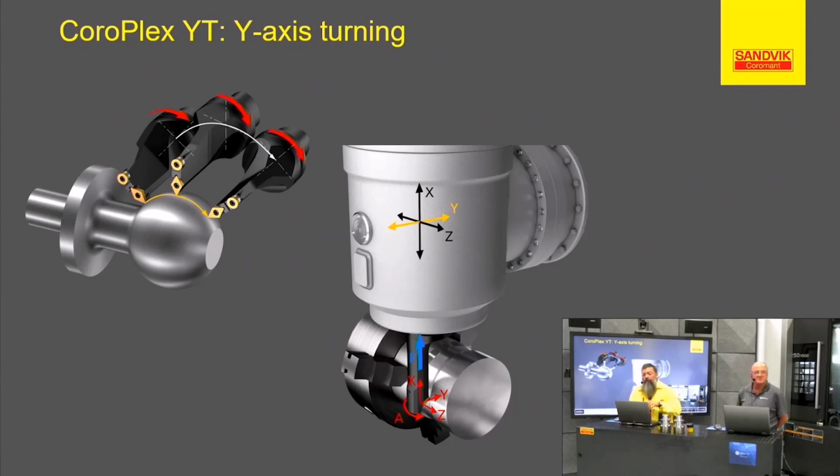So when we look at the overall benefits of this tool, we have inserts on both sides, and we have indexability within the tool without returning home for a traditional full tool change cycle on a multitask machine. We're talking about reducing chip-to-chip time from 18-20 seconds, depending on machine capability, down to 4 to 7 seconds.